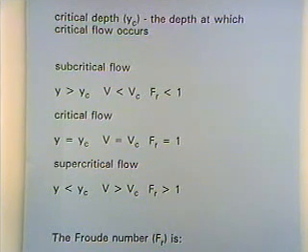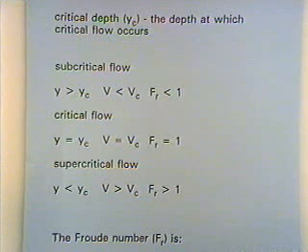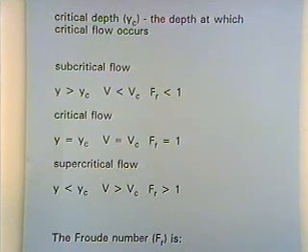So subcritical flow means the water's not flowing very fast. And so any of the natural streams in Texas, you're dealing with subcritical flow. Maybe if you get up into Colorado and the Rocky Mountains where there are very steep, fast-flowing streams, you may have some naturally flowing supercritical flow. But in man-made structures, in the chute of a spillway, and a lot of concrete hydraulic structures, we'll deal with supercritical flow. And so subcritical flow, the water is flowing deep and slow. The Froude number is less than 1.